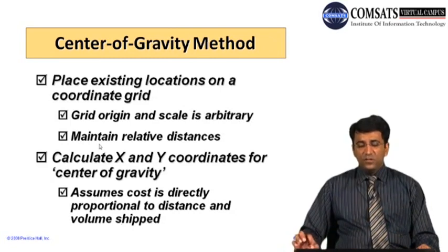But by plotting the different locations on that particular graph, you will have to take into account the relative distance of the particular locations. Now after plotting all of these locations on the graph, you may calculate the x and y coordinates for the center of gravity.